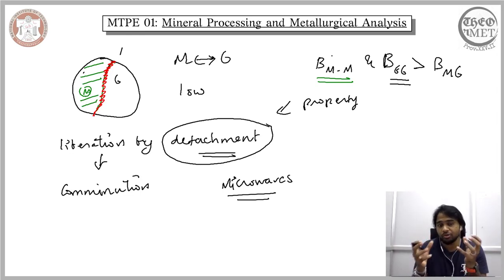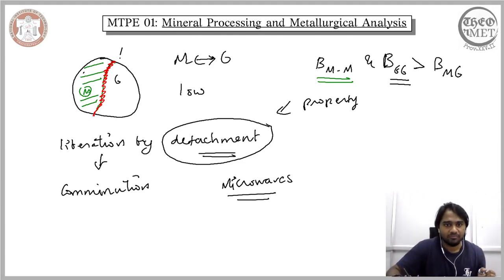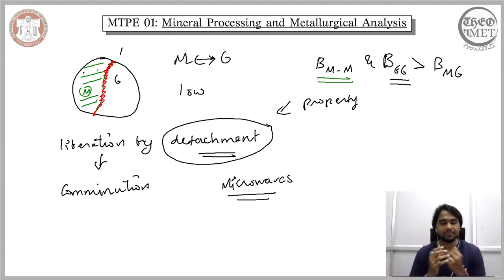And again, this is property dependent, and it cannot be employed for all mineral particles without prior knowledge of their properties. If we employ it for all the mineral particles, then we cannot expect a clean breakaway of this interface, and essentially what we will end up with is fragmentation of the larger particles. Now, instead of regular comminution, you will be using microwaves and stresses to do it. So again, that will be economically a huge burden on us.